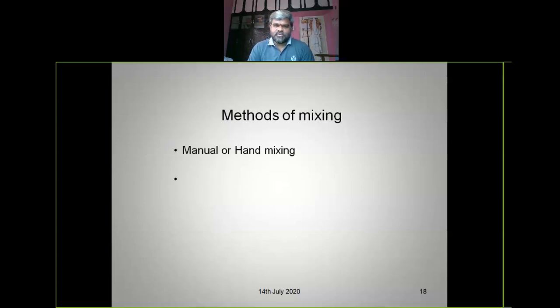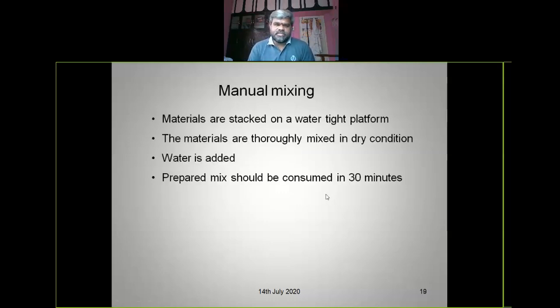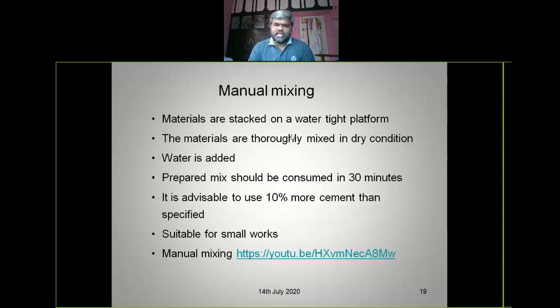Methods of mixing: there are two types of mixing, manual or hand mixing, and another is machine mixing, right? Manual mixing means materials are stacked on a watertight platform. The materials are thoroughly mixed in dry condition. Water is added. Prepared mix should be consumed in 30 minutes.